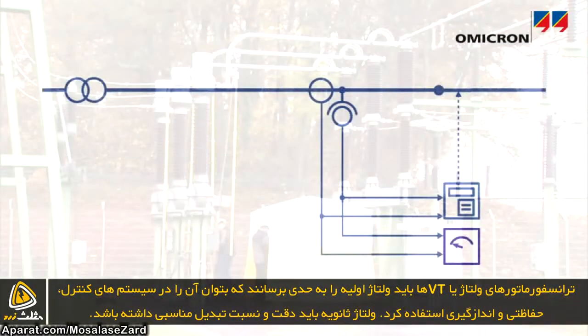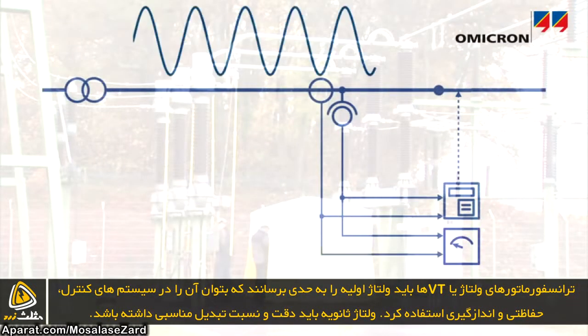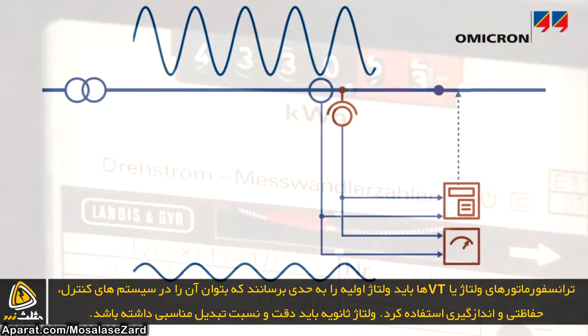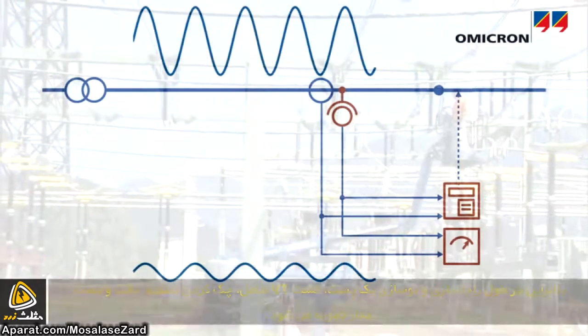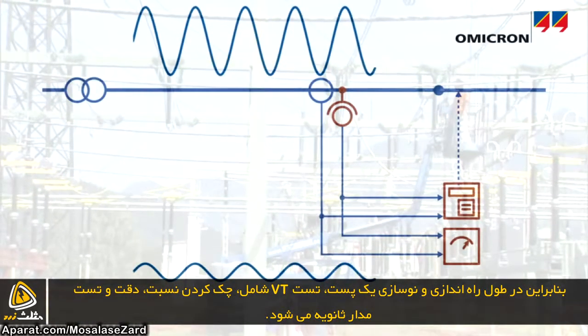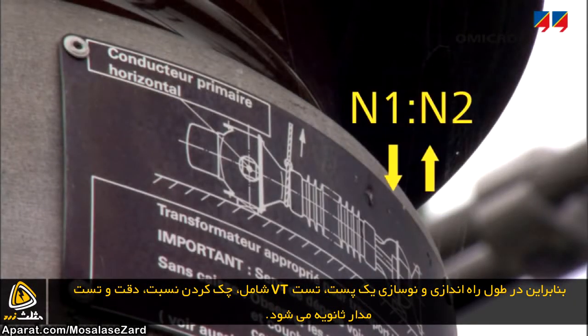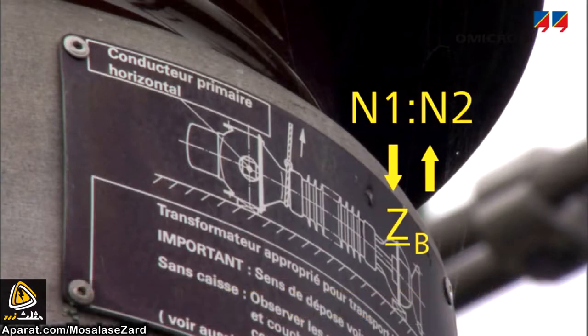Potential or voltage transformers, or VTs, have to transform primary voltages into levels that can be applied to control, protection, and metering systems, with sufficient accuracy and correct polarity. Thus, during the commissioning or refurbishment of a substation, testing a VT includes checking its ratio and polarity and measuring its burden.